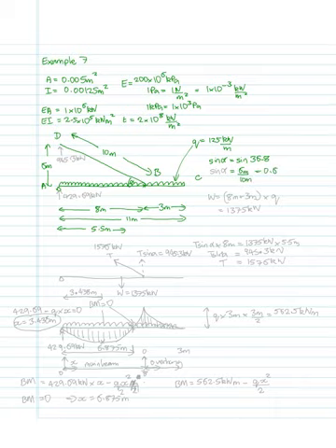So we know that sine alpha is going to be equal to 0.6. So let's calculate the total load acting on the beam. The total load I'll call W. 8 meters plus 3 meters, which is the total length, multiplied by Q, and that turns out to be 1375 kilonewtons.